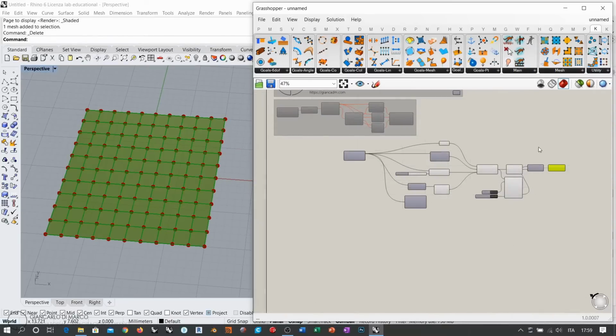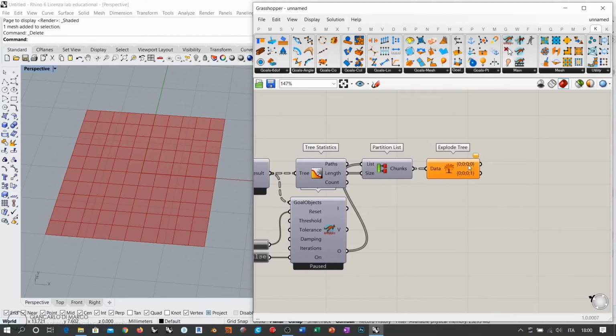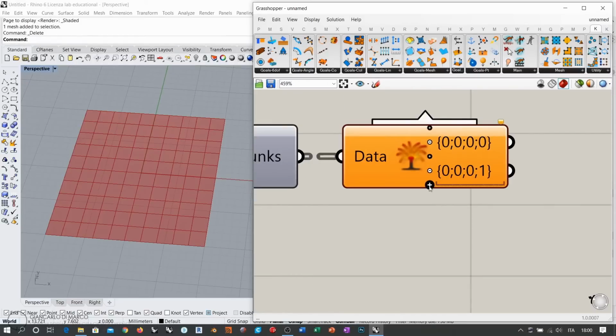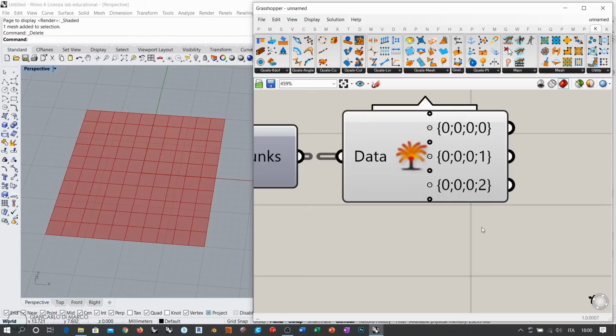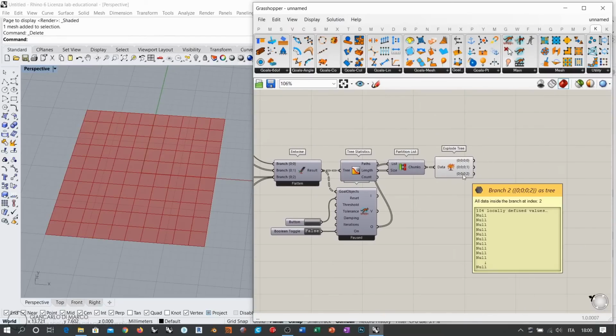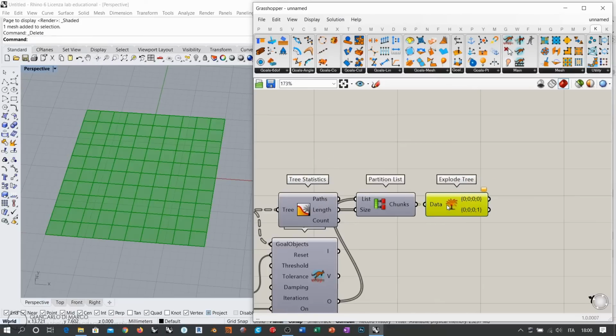And finally, if I turn off everything here, I have access to 0000, which is the mesh. 0001 are the lines, which are basically the elastic forces, so the springs. And if you want, but it's not relevant, in 0002, you have the output for pressure and anchor. But remember that pressure and anchor don't have a geometrical preview. Okay, so you see, you get all these null objects. So you might want to simply avoid having this branch visible because it is useless.